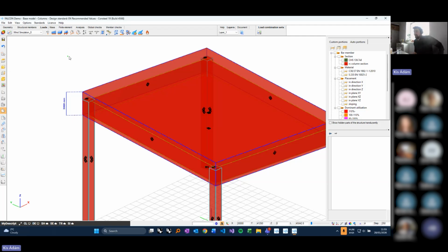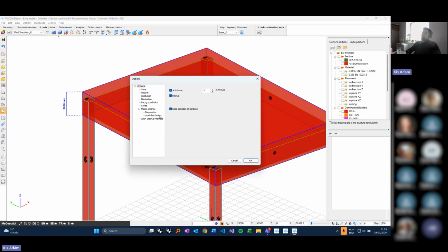And this is where I would like to also introduce during this demo our newest feature regarding the load transfer surfaces, or the extended version of these, which means actually a simple, let's say, additional approach. During load distribution, you can consider with Consteel 19 a certain limit value.